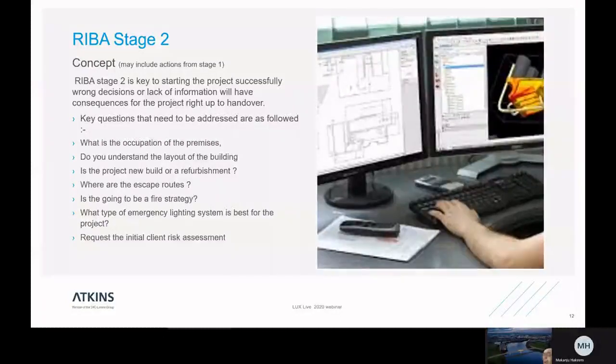So at concept design, you're really putting down on paper the basic principles of the emergency lighting system. Unlikely that you will do drawings at this stage, but certainly you should be having conversations with the client as to what type of emergency lighting they would like, particularly, and what it is that they are trying to do. If it's as simple as a scout hut or a church hall, self-contained emergency lighting only fittings may well be suitable.